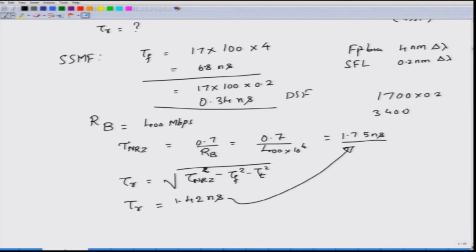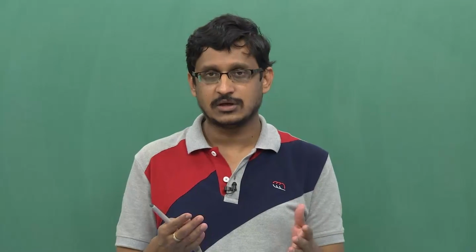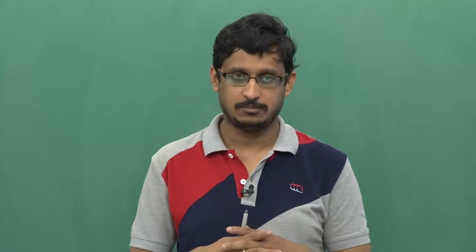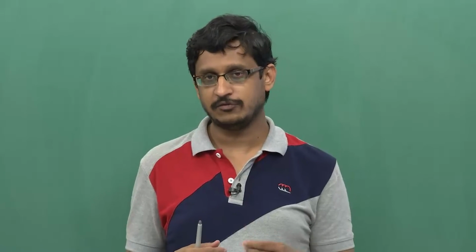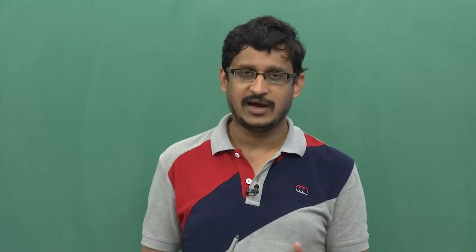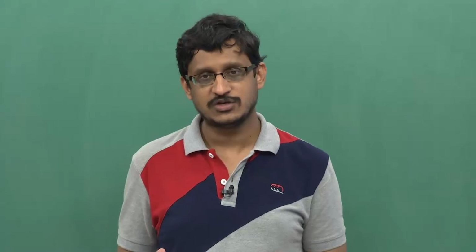So, in this way you have to design the components in such a way that you are transmitting signals at a given bit rate with the overall goal of maintaining the rise time budget as well as the power budget. For different fibers and different operating conditions, the rise time budget will also change, and you can use MATLAB to calculate all these values. We will supply you with a small MATLAB program which you will be able to use to come up with the maximum value for propagation distance and for the rise time of the system. Thank you very much.